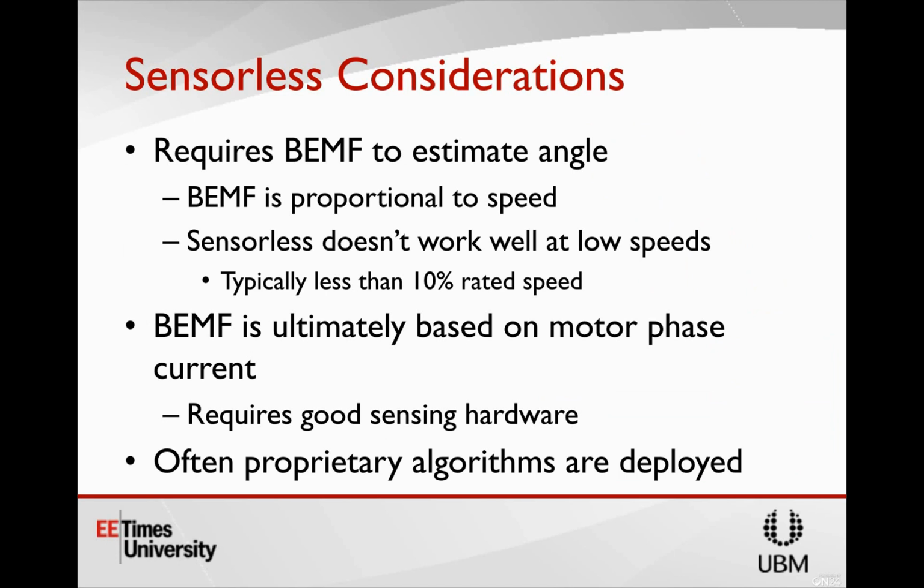And so what that's going to do is degrade how good your field-oriented control performance can possibly be, because you don't have as much resolution as you really could use in your application. Being able to balance the range of resolution with the maximum peak current you're ever going to see is really an important thing to consider. It can be a little tricky to leave enough headroom, so that if you need to drive a bit more current than the motor rated, you can still sense it and you're leaving yourself enough room to have good resolution. It can be tricky to balance.